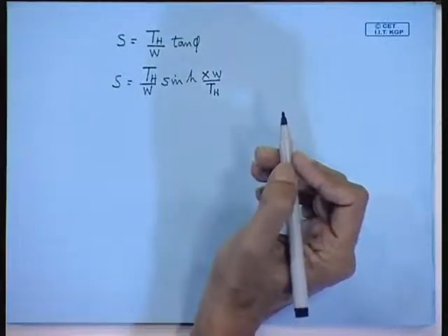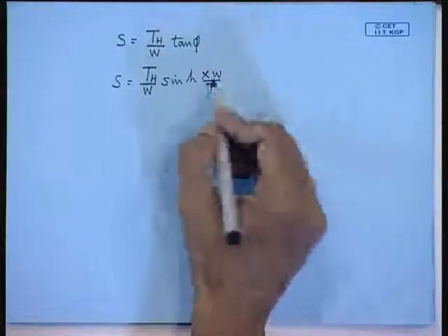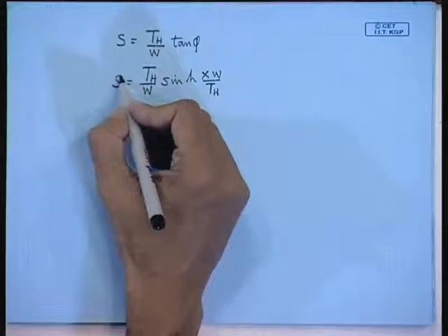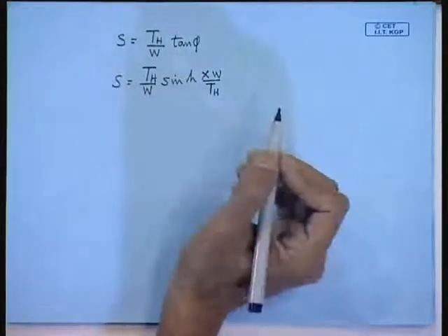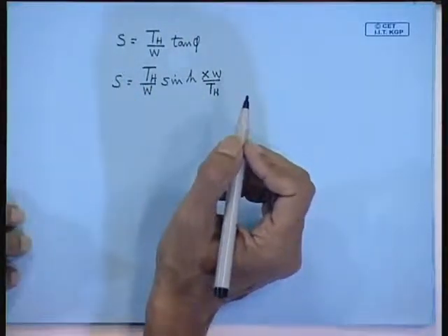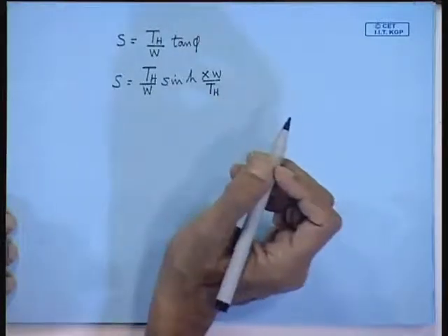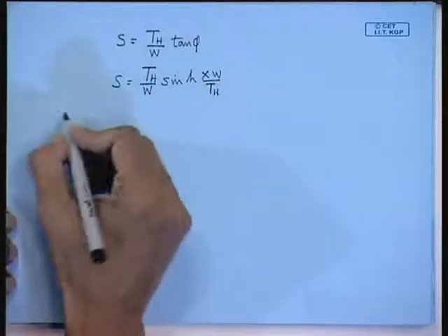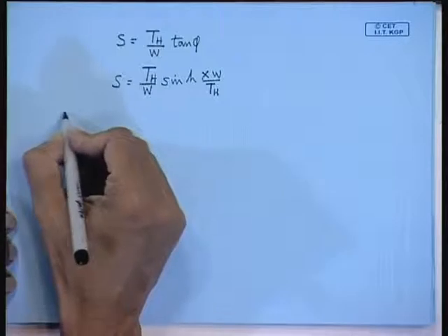So TH is how much? T cos phi, that we have found out from this expression. If you know the angle, you can find out that TH expression, TW cos phi. So the only unknown variable is x. If you know x, you can find out the length of chain cable. Now this is one expression we can use, and the other expression is, what is the expression for Z plus H?